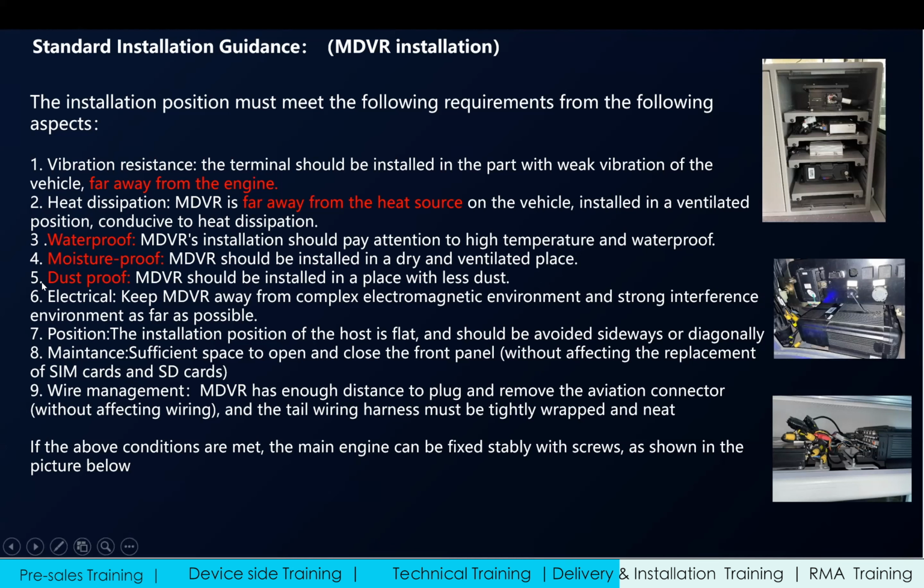Fourth one is similar. The fifth one is the dust proof. Keep the surrounding environment of the MDVR clean, because if any dust goes inside, it will also make our MDVR run slow. And for the electrical environment, it's the same. If you put the MDVR inside the console or a very complicated electric environment, one is that it will not be good for maintenance. The other one is that there will be some conflict with our system.